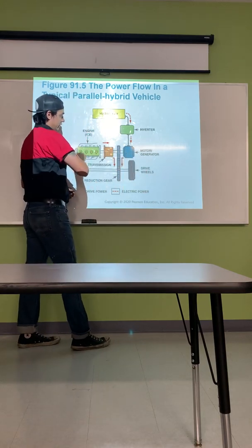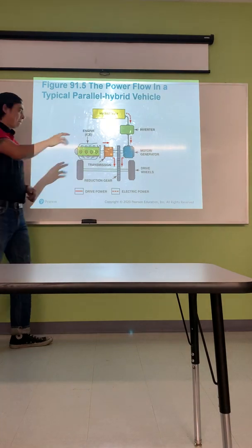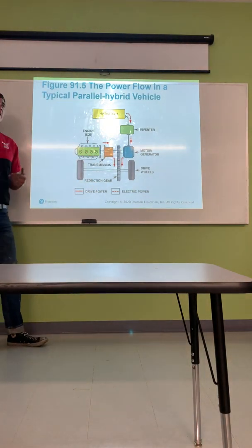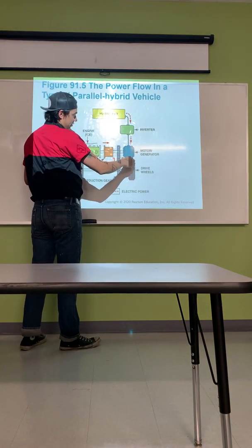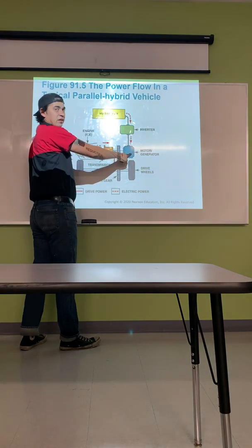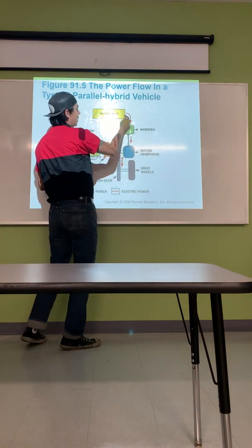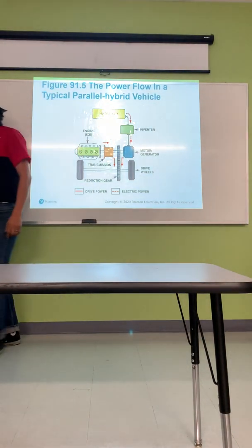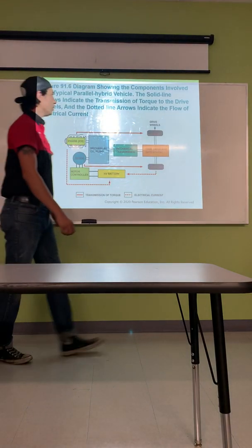And then also at the same time, I would say most hybrid systems now have what is called regenerative braking, where it converts the motor into a generator, which then, when you start to slow down, the motor is not propelling the car anymore. Now what it's doing is it switches polarity inside, which then sends power back into the battery. So we're actually charging it while we're driving it. And it's actually pretty cool how they do it. And we also have plug-in hybrids as well.